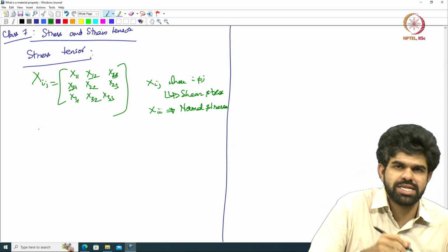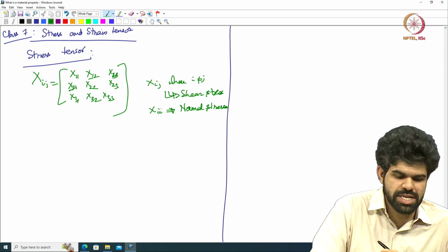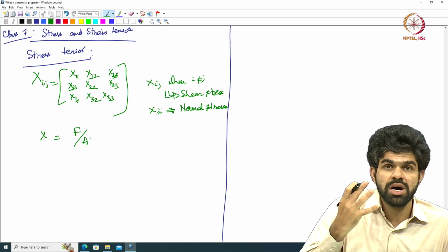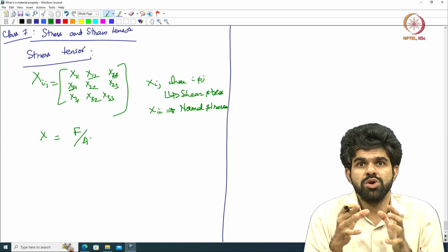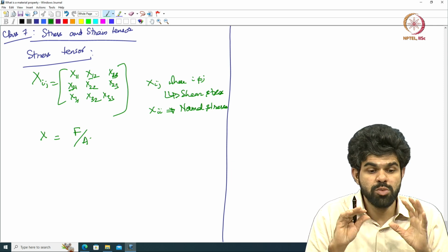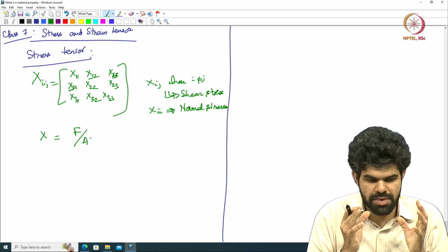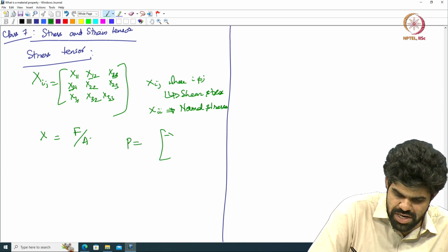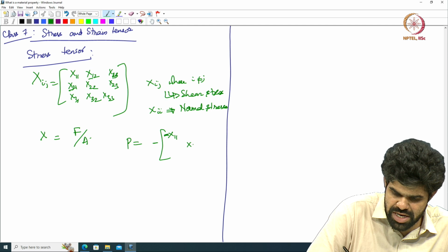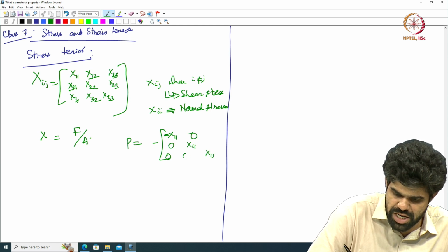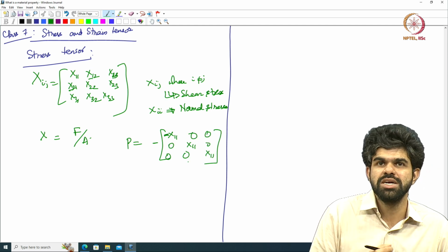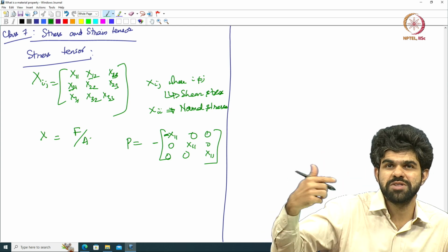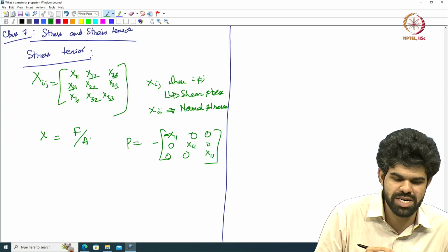But what is stress, right? How did people teach us what stress is? Stress is nothing but some sort of a force on an applied area. Pressure is what is called homogeneous stress, right? Sorry, pressure is isotropic stress. Pressure is just the negative of stress, but the stress is isotropic in all directions. I do not have any shear components, right? So this is the definition of pressure. So pressure is a particular case of applying stress to the material, right?